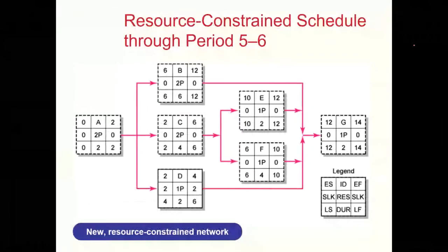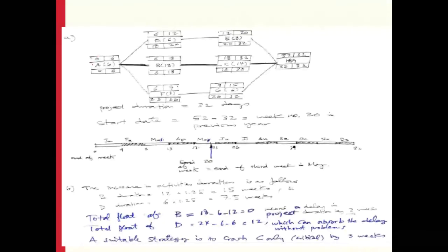So to do this, the simple task required was for you to do a simple CPM method to calculate the overall duration. So this calculation has basically given us that this project is going to take 32 weeks to complete. And we know there are 52 weeks in a year. So 52 take away 32 gives us around the 20th week, which may be around May time. So we will make a suggestion that this project should start in the beginning of May, so that we have got enough time so that the dam could be completed before January.